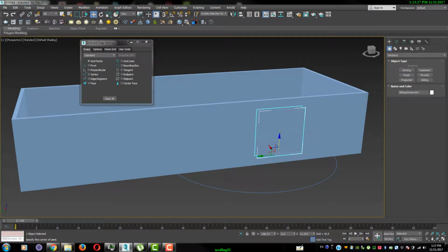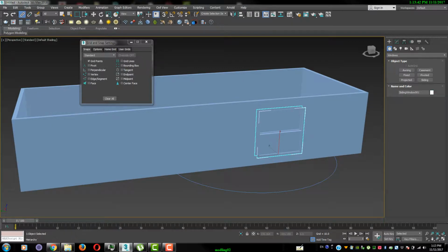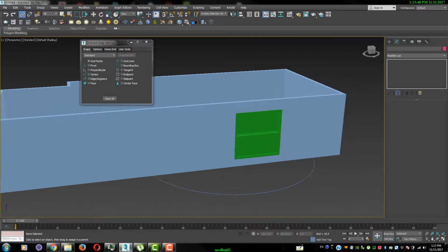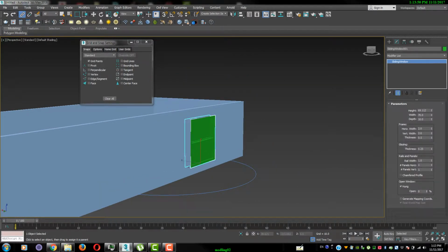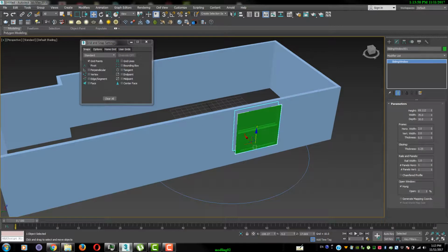So we go to link. I move my mouse over the window, I hold the button and move the mouse over the wall and release my button. Then Max now understands there is a window here. Okay, here is a window and there is a hole. Another way: I activate my snap object, I remove grid, I choose edge and segment.